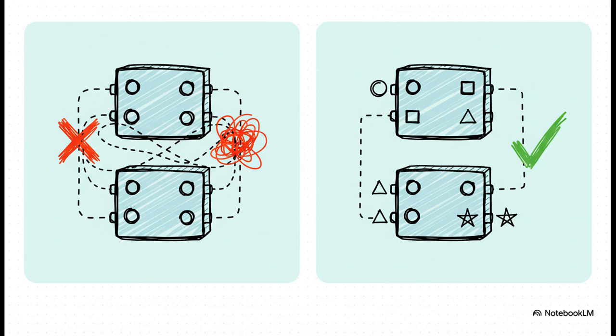Now, when it comes to actually wiring up these modules, Verilog gives you two choices. You could connect them by order, which means the first wire in your list connects to the first port, the second to the second, and so on. It's simple, sure, but it's also super risky. Imagine you have 50 ports and you get just one out of order. It's an absolute nightmare to find that bug.